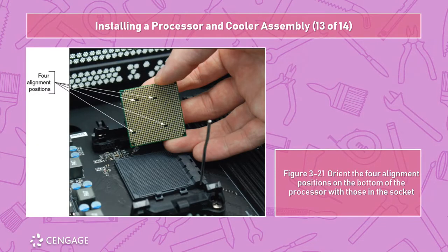So you can see those pins there, not the easiest because it is kind of face on, but you can see in the socket that there are little holes that are going to slot in. But you see it's also the same concept of the lever that'll help lock it into place, and in the bottom left of the CPU, the pin face, you can see the little yellow triangle to orient which corner is supposed to go where. You see the alignment positions.